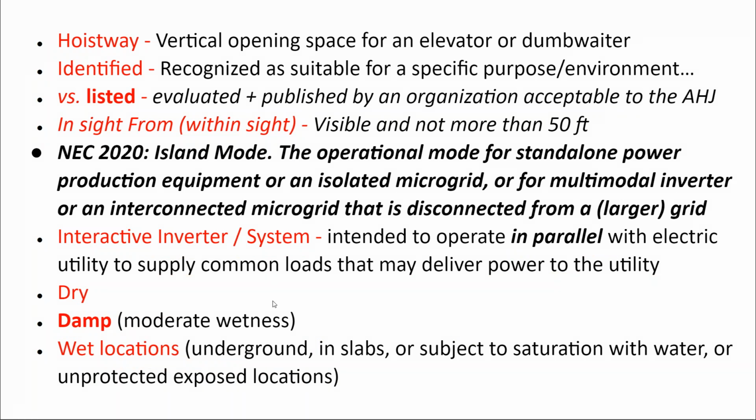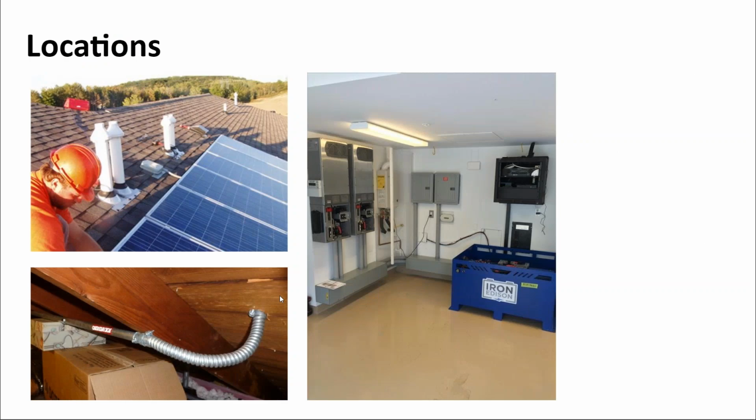But MC cable specifically is only rated for damp locations, so there are only specific spots where it can be outside. What that means is if you're coming out underneath a soffit, you might only have a couple of inches on the outside before you have to go into a box, so that the soffit is still protecting that cable. And if you're in a very rigid jurisdiction, you might have to make that transition before you come out of the soffit, although flexibility does have its uses.